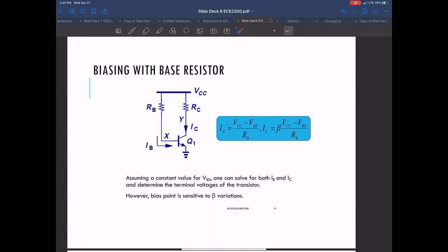Our input, the microphone in this case, would connect here, and because this has a source resistance of, again, say 200 ohms, if this is something like 100 kilo ohms, this guy's signal is basically going to sit on top of whatever voltage we generate here, and the modulation will go through okay.